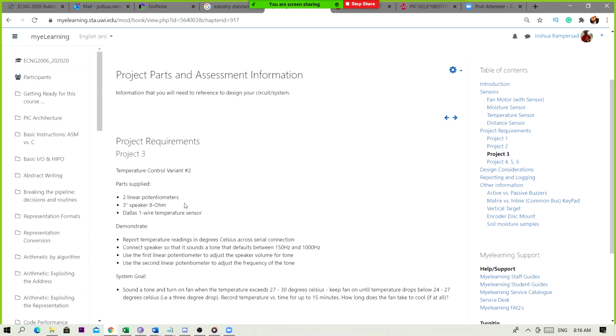Oh, okay. So you have 2 of them, right? Yep. So if you wanted to figure out the position of the potentiometer, you'd be generating a varying voltage, right? Yeah. Okay. And you have 2 of them, so you need 2 different channels, right? Yeah. Okay, good. And they're both resistances, so just connecting it straight to the pin wouldn't give you a voltage. You have to build some circuit where the voltage output varies as you move the part, right? Yeah. All right. Any questions?